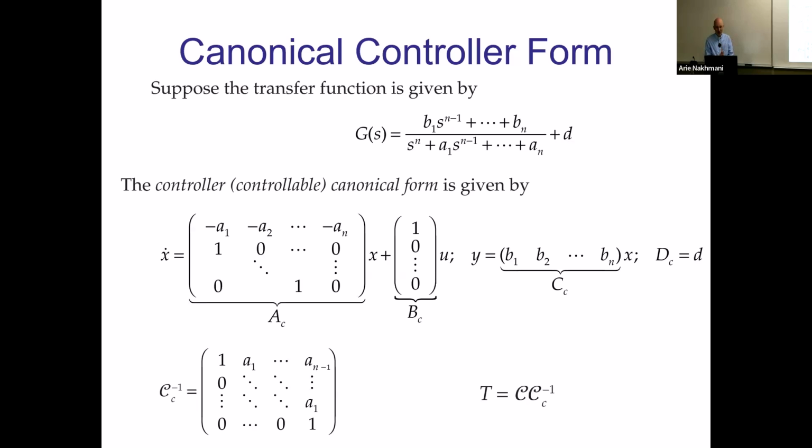It's always controllable. The controllability matrix is invertible, and I even computed explicitly how it looks. So it will look like 1 on the main diagonal, zeros below that main diagonal. So it's a triangular matrix, an upper triangular matrix, okay? Here you have coefficients a1, 2, 3, 4, 5 to n minus 1, because you have n minus 1 columns left, right? And then you copy that by diagonals, all of the coefficients, okay? This is how this matrix will look, the standard way to represent it.